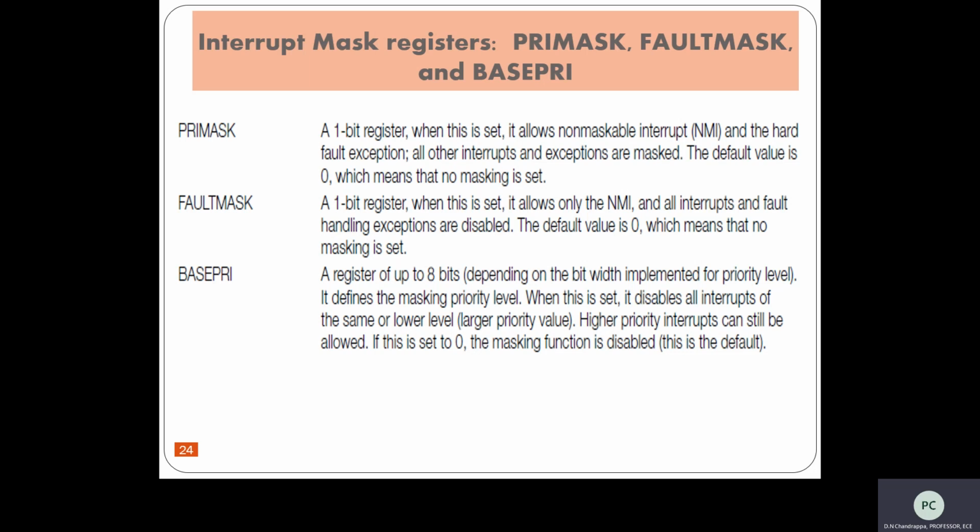Second one is the FAULTMASK. Again here also there are set and reset operations. If it is set, it allows only non-maskable interrupts, and all other interrupts and fault handling exceptions are disabled. If it is 0, it means that no mask is set.